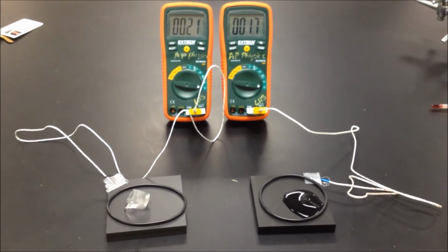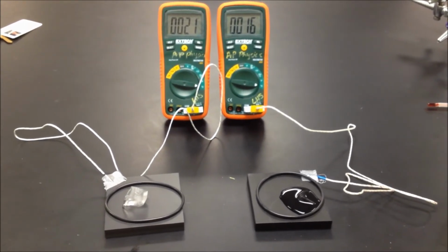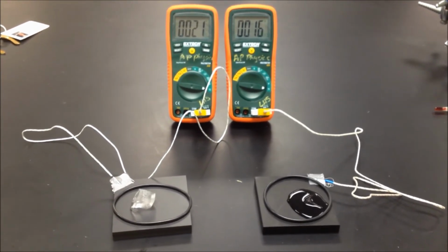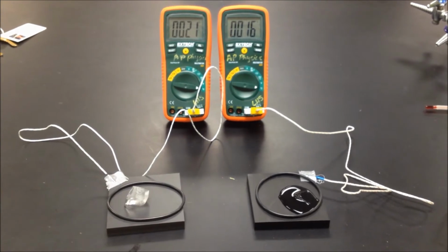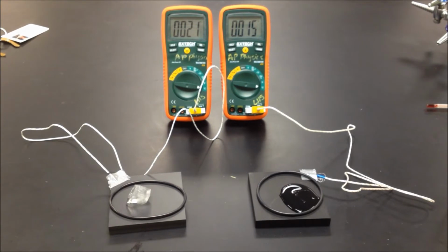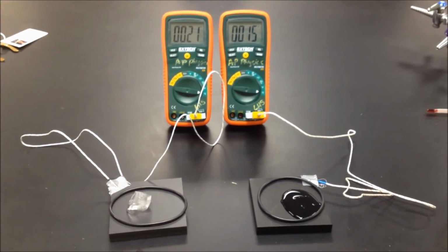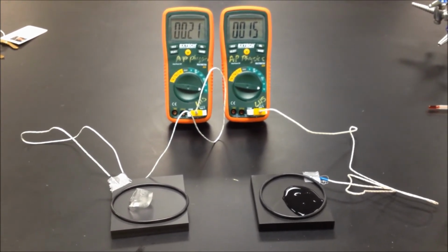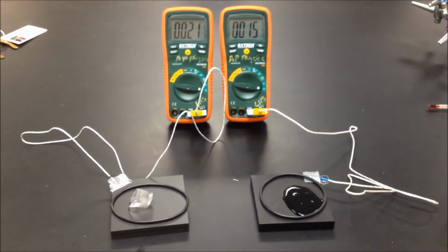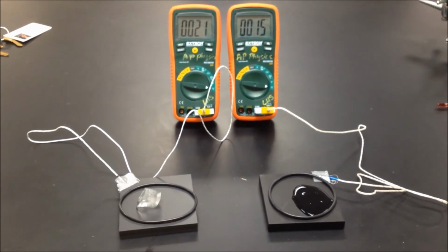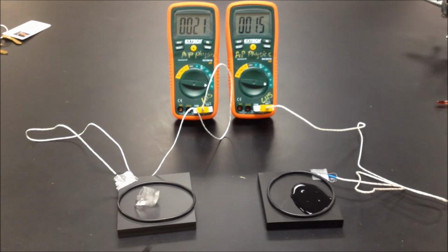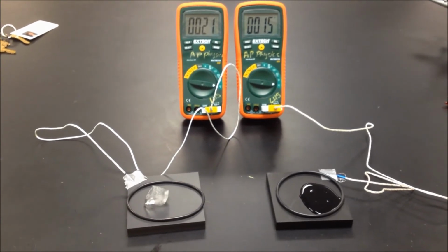Both of these ice cubes were similar in mass when I placed them on the blocks, and of course, both at 0 degrees Celsius. However, the ice cube on the aluminum melts quicker, meaning there is a greater rate of heat transfer occurring between the ice cube and the aluminum, as opposed to the ice cube on the plastic foam block, which is almost not transferring any heat whatsoever.